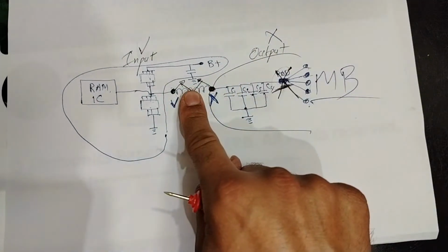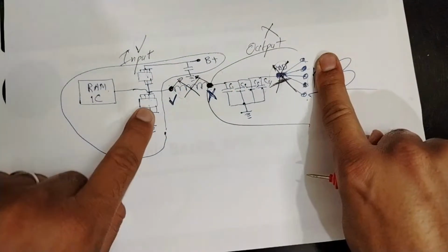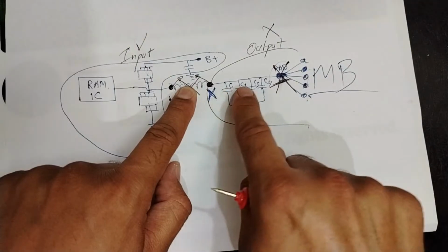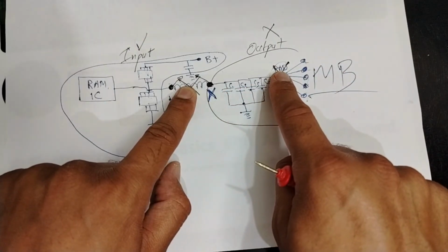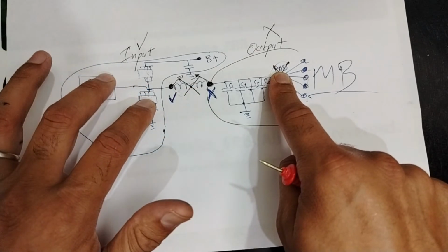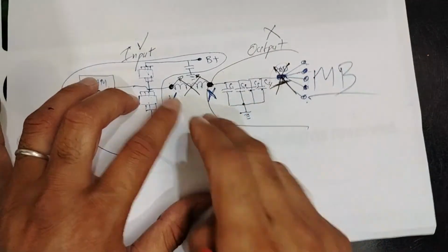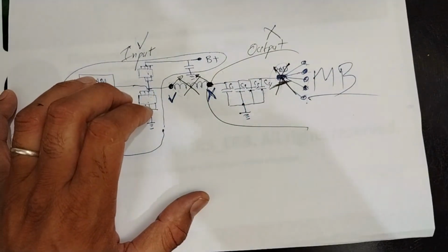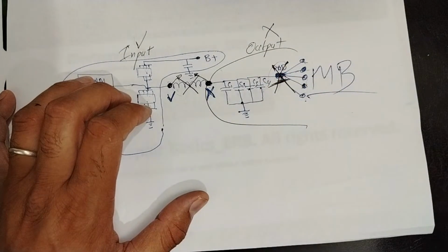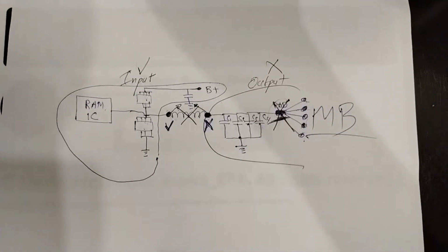I remove just the coil and I find the short on the side. So all those are good. I don't touch any one of these. Okay? Just the coil. Now I will not touch anything here. I will just remove the pad. So this process will help you keep these components good. You will not touch anything. Just to summarize, this is the shortcut of understanding the short. I will remove this one because I have an iron that is bigger than the pad. So I will do my best, my friends.